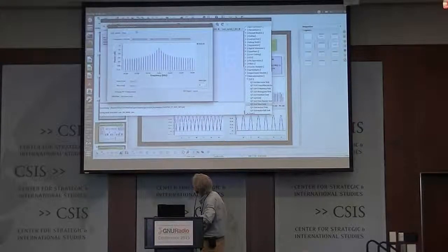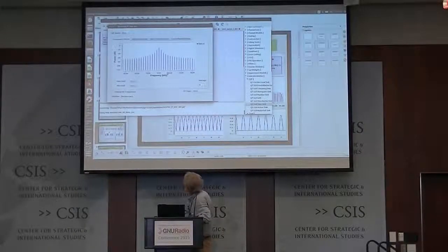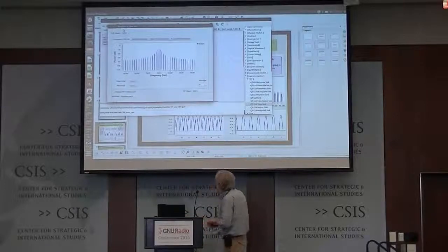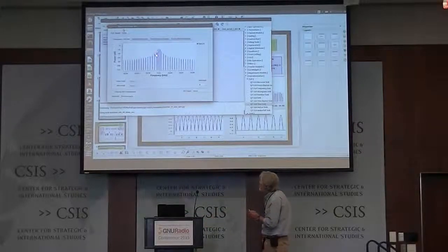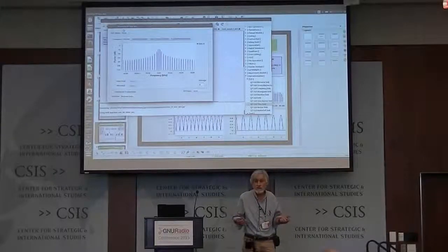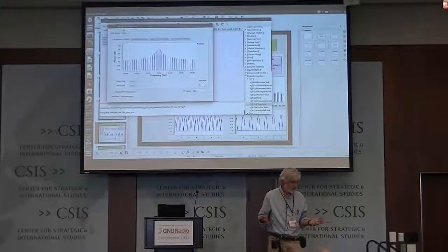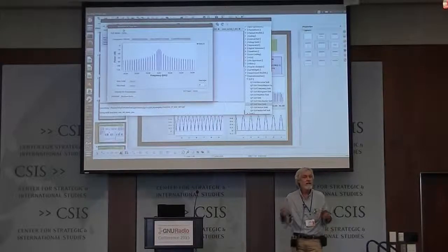I use the 1 kilohertz frequency, so this is spaced 1 kilohertz apart, 2 kilohertz apart because of the squaring. Okay, now if I change the full wave here to false and make it the half wave rectifier, I get those additional components in here. So the interesting question to ask the students is, why do I get this in the first place, and then what implications does it have?